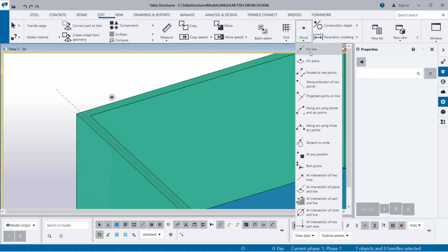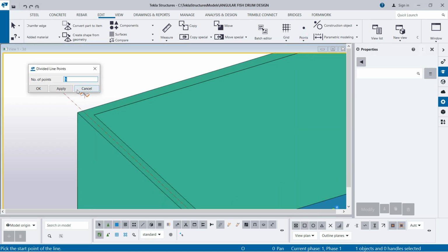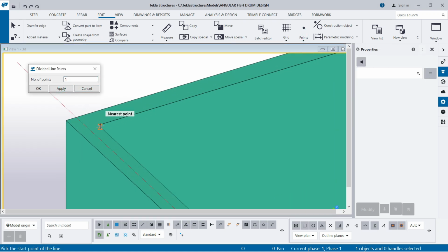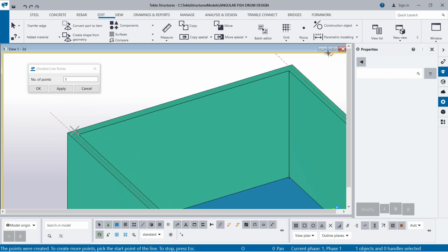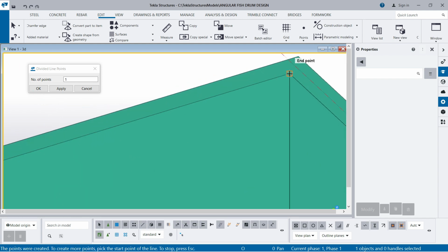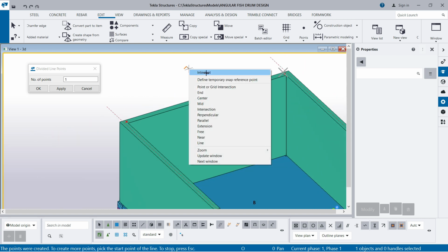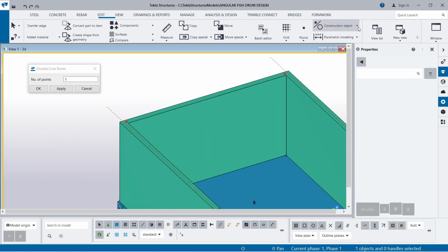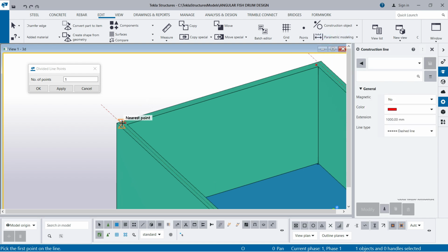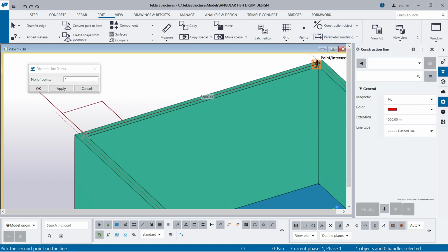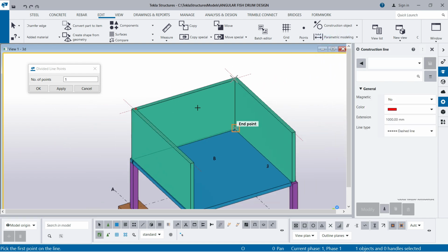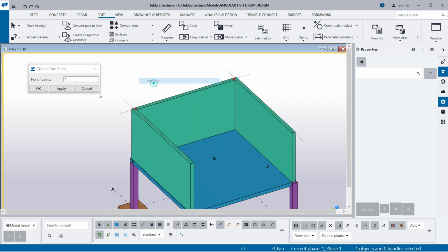Then I'll pick on the point. So I will use online. I pick that point. I apply this just once on this line. I pick the first point, move my hand this way, pick to have it placed right there. Come to this other end, I pick from this point, have that point placed. I have 2 points. I interrupt this and then I come to construction line. Pick that, pick the first point all the way, second point to have it just like this. Now we are good to go. I interrupt this, click on the OK options.